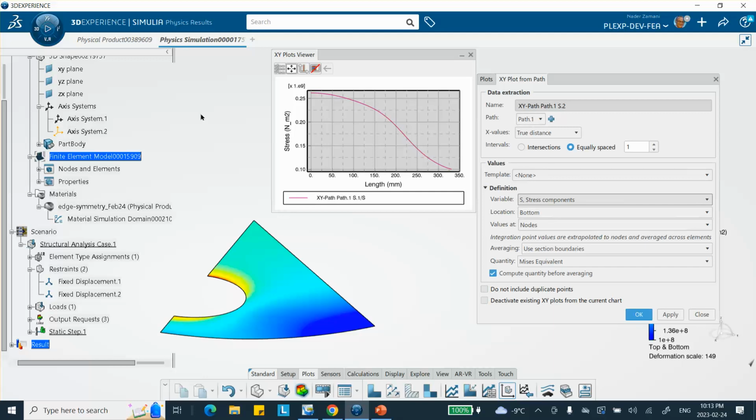In the other video that I did, inertial relief of a rotating disc, I did not have any restraints. Here I had to have them, because I specified symmetry planes. That's why it worked. There I didn't have any restraints, and I applied inertial relief, and it took care of it. I'm a bit surprised here that there's nothing stopping this thing from moving up and down, but still it ran. So that's surprising to me. Good luck.